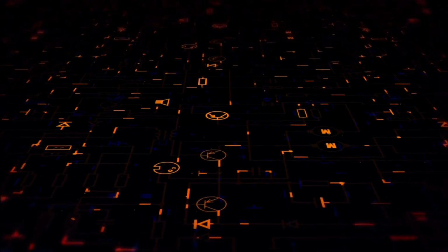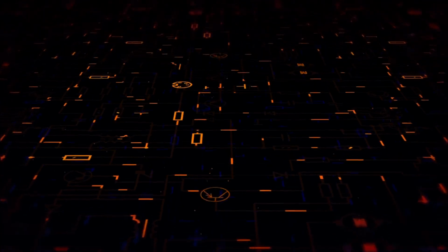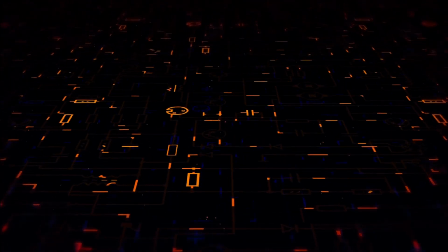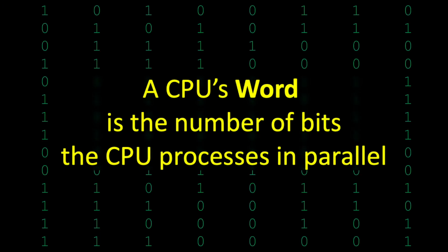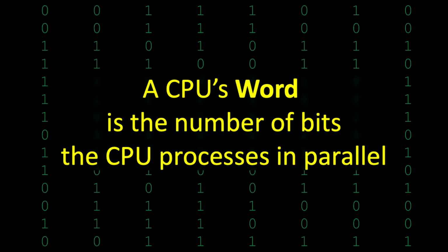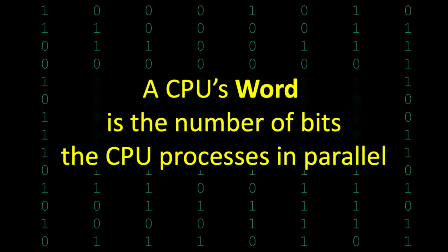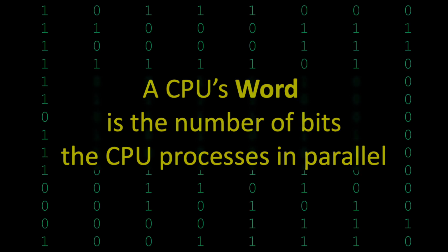In order to accomplish this parallel scaling, we will introduce some additional control circuitry made from the Boolean gates we established in the previous video. The size of the parallel scaling depends on the word size. A word consists of an ordered set of bits that we use as a standard parameter in the operations of a processor. The number of bits in the set constitutes the word size.